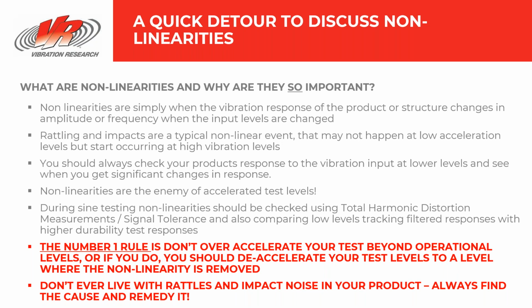This can create lots of high frequency energy that you haven't put into the system, or can cause problems in controlling a test, because you're no longer putting in any energy at high frequencies since the system is generating all these high frequencies. The main thing here is you should always check your product's response to the vibration input at lower levels and see when you get significant changes in this response. This is why you should be monitoring what's going on inside your product.